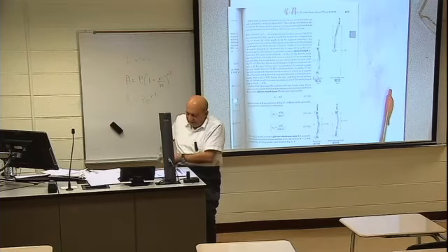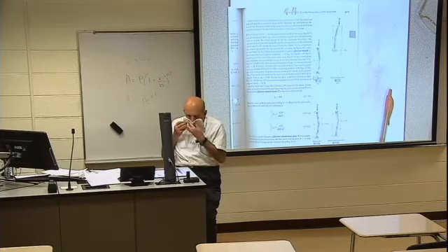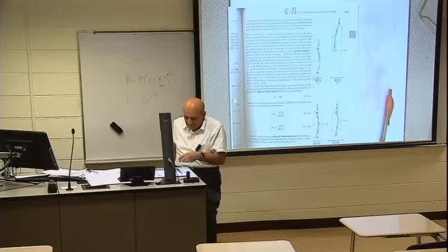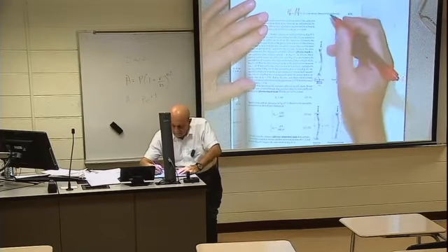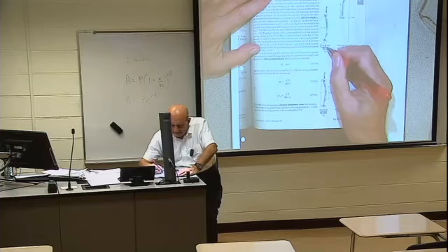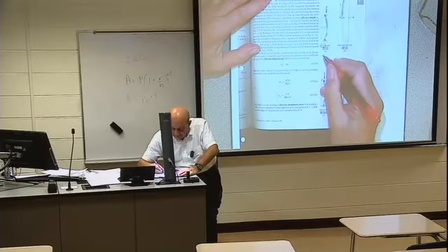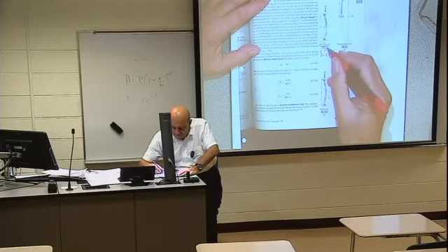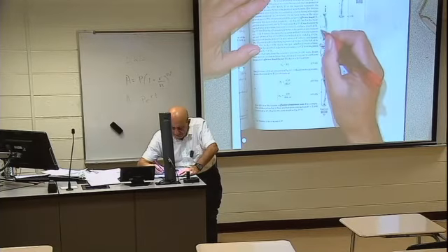And that is pinned ends in the book. That is our book. Means simply supported. So K, big K equals 1. So L effective equals L.